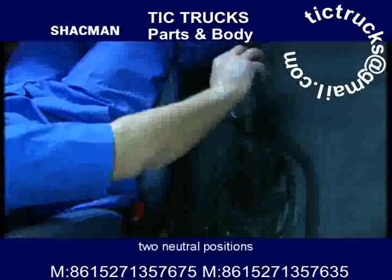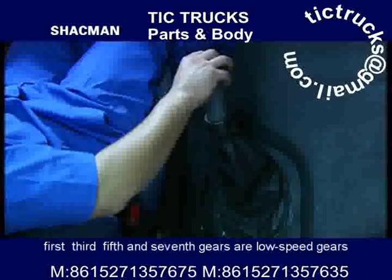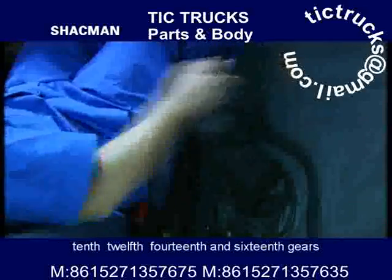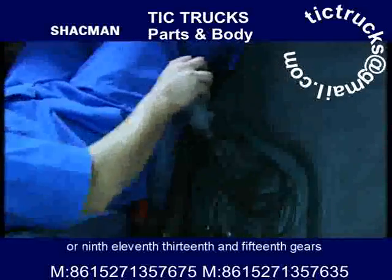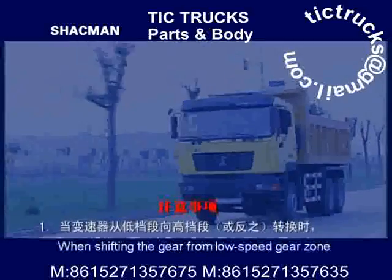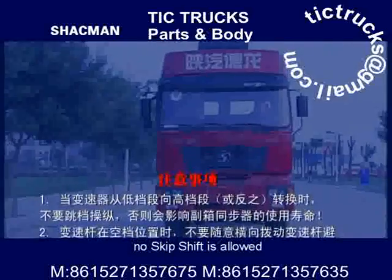2 neutral positions. The 2nd, 4th, 6th, and 8th gears, or 1st, 3rd, 5th, and 7th gears are low speed gears. 10th, 12th, 14th, and 16th gears, or 9th, 11th, 13th, and 15th gears are high-speed gears. Instruction: when shifting the gear from low-speed gear zone to high-speed gear zone, or conversely, no skip shift is allowed.